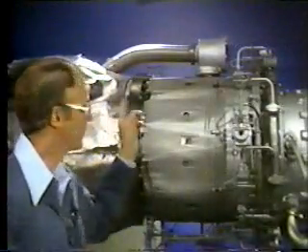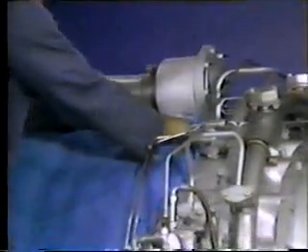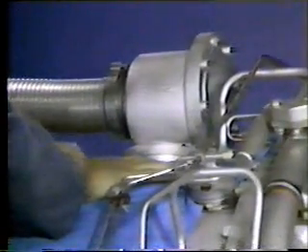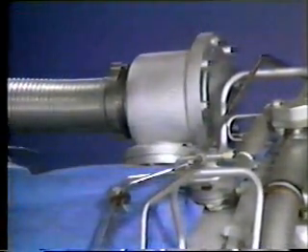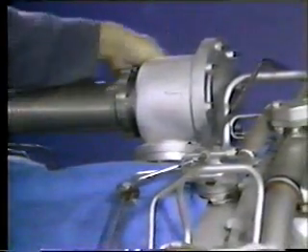Routine maintenance on the bleed air valve should be scheduled after the first 1,000 hours of operation and each additional 4,000-hour interval. More frequent maintenance may be needed in hostile environments. And since the valve is located on the hot section of the engine, allow time for cooling before starting this maintenance operation. Begin this operation by taping cloth around the duct which the bleed air valve is mounted on. Be sure to cover the opening in the heat blanket to keep parts from falling inside the blanket.